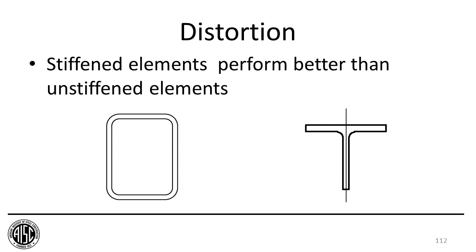All right, so what is typically done in a cambering machine is a two-point ram bending. And if you take a look in the design guide, it discusses that briefly, but I know that there's some work being done on a camber design guide too, so it'll have more information on that when that comes out. So the typical fabrication shop can provide the camber. They would hire a bender roller if they had to camber something that exceeds their machine capacity. Either they could heat that member up or they could send it to a bender roller. And the bender rollers sometimes get big contracts to camber the members too.